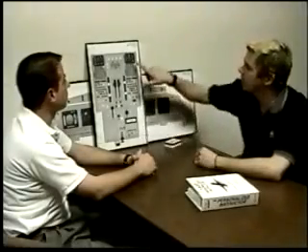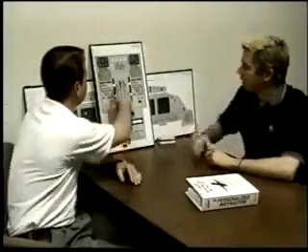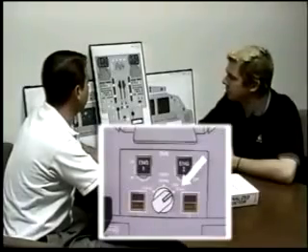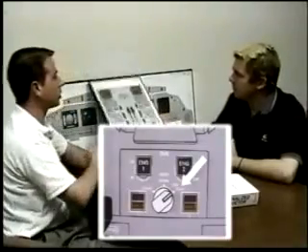So just to recap that, the only time I select config 3 is when I'm doing it for proficiency or if I elect to do so out of a non-ECAM driven situation like wind shear. You go to start engines. You go throttles idle, mode select, ignition start. What are some items you're looking for when you take the mode selector to ignition start?